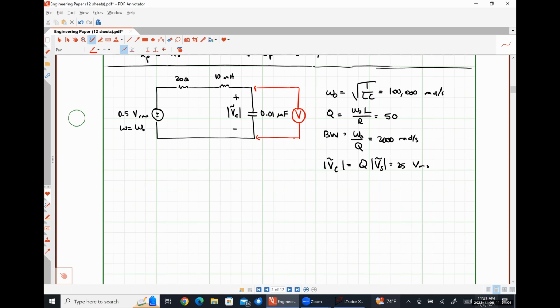So gigaohm is a bit high. I would argue somewhere between 100K to 1 megaohm would be a normal thing. So let's see what happens if we effectively put 100 kiloohms of resistance in parallel with this guy, representing the impedance that we would introduce into the system by connecting our multimeter, right? If we're trying to make a practical measurement on this system, to this point, we've always assumed that our measurement equipment isn't going to impact anything, but it very much can, okay?